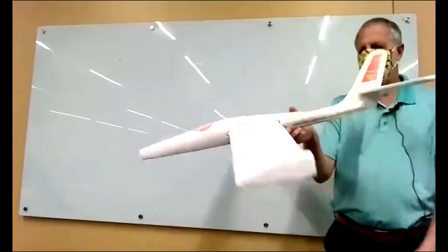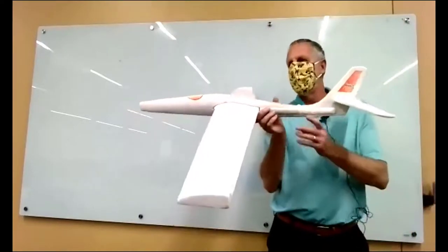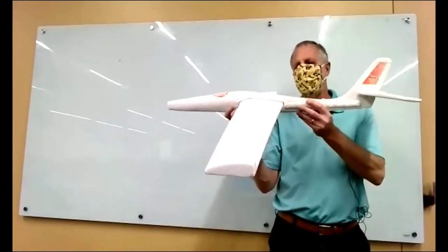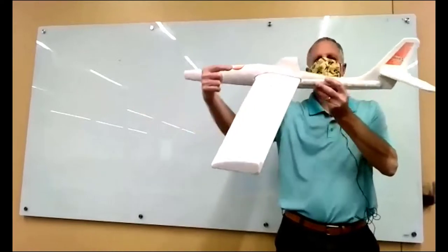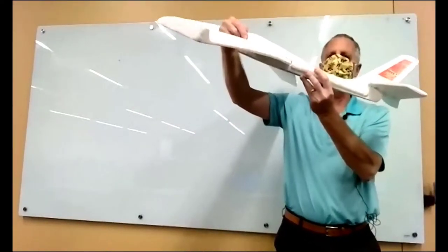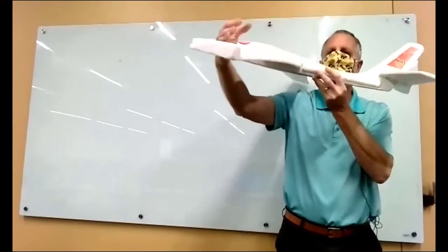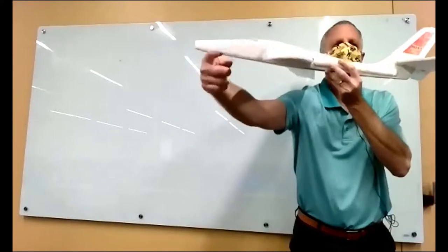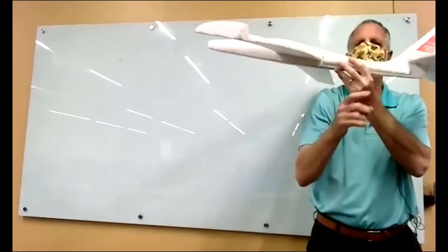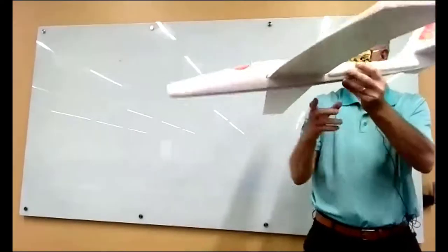All right, and while we have the foam airplane, that lag in the downwash, we could talk about that. I've drawn pictures, but you've got the flow coming through like this. If you rapidly pitch the airplane up, the angle of attack of the wing changes, right? So the lift changes and the pressure distribution changes, but it takes a while for that wingtip vortex to get back here, and that's the lag. The change in the vortex from that sudden pitch up.